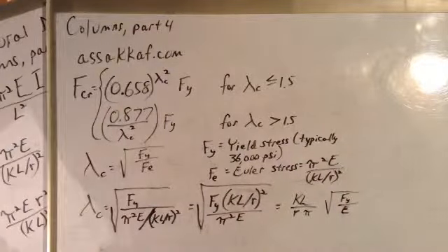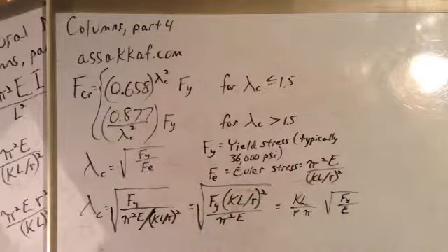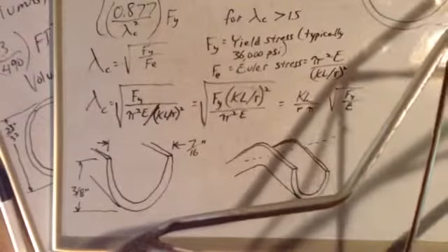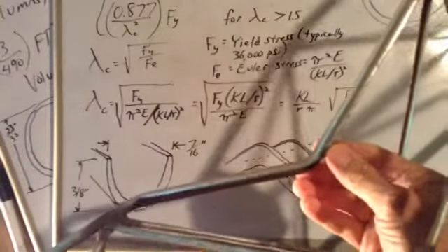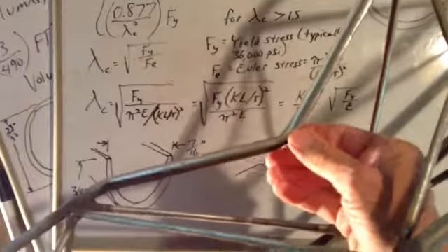Okay, now we're going to see what these formulas say about the strength of the tail boom mock-up of the steel stork. This tail boom has a top flange, two bottom flanges, and zigzags connecting each flange to the other two flanges. This is the failed component of the tail boom when it was tested to destruction.